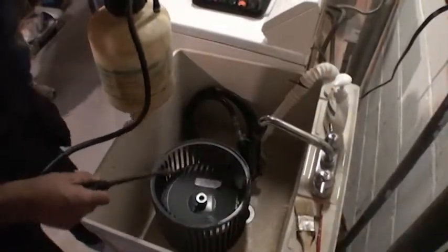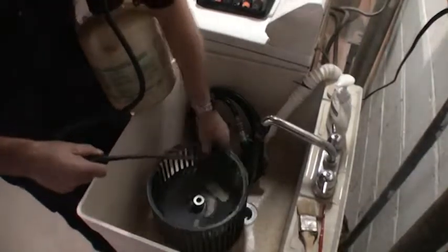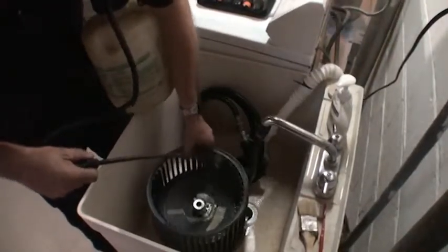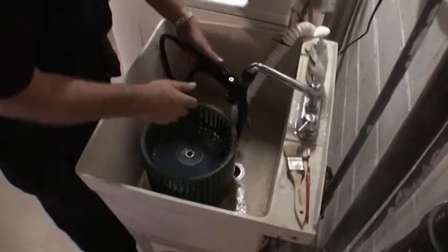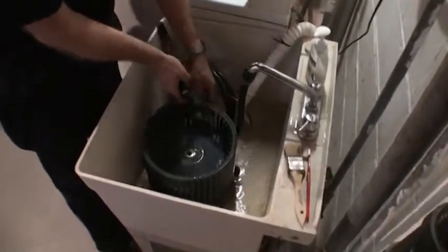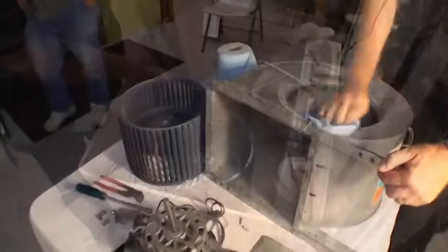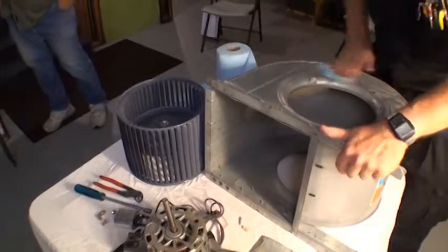Chemically clean the blower blades. If the furnace has an electronic air cleaner, you will need to chemically clean this as well. Following the chemical application, spray off the blades with water and dry blower blades completely. Thorough cleaning of the blades will provide a savings for the client on their energy bill. Clean the blower frame before reassembling the blower.